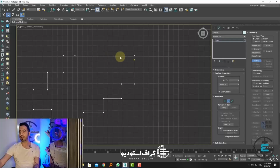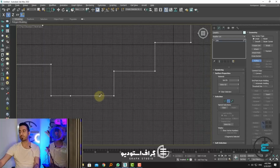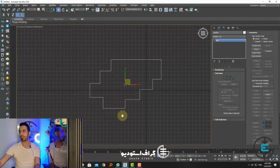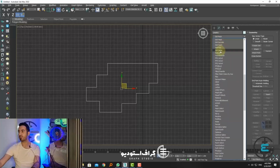Here I, for example, select this. I put it here. I activate it here. I say in the X axis, for example, go one meter, this vertex. Well, and now when I come to this and apply extrude to it, you see the places where I hit refine came and exactly dropped a connection there. And this makes our work very easy. And now I can do convert to edit poly here. You see how much it is connected to each other.